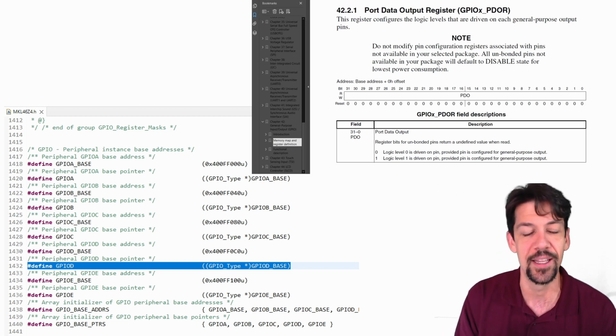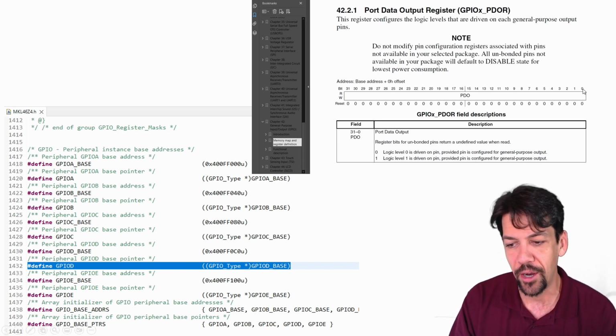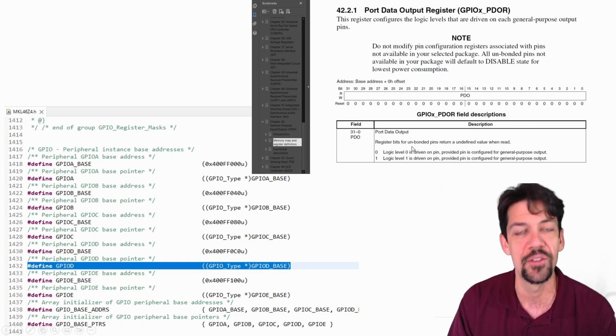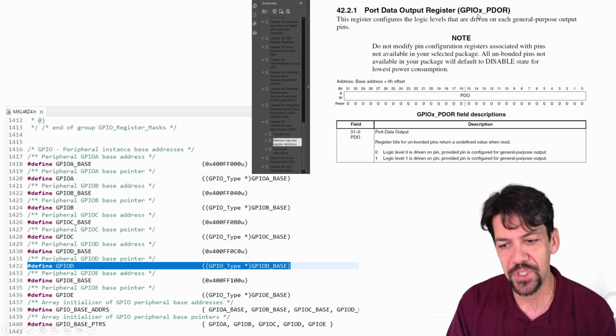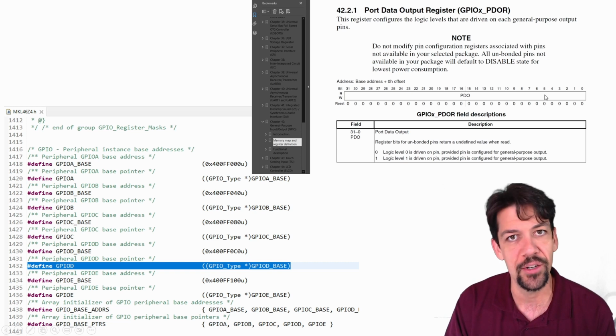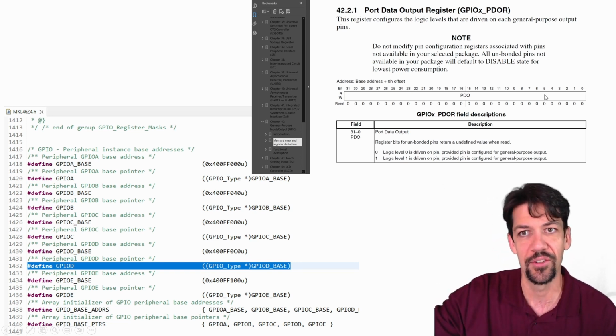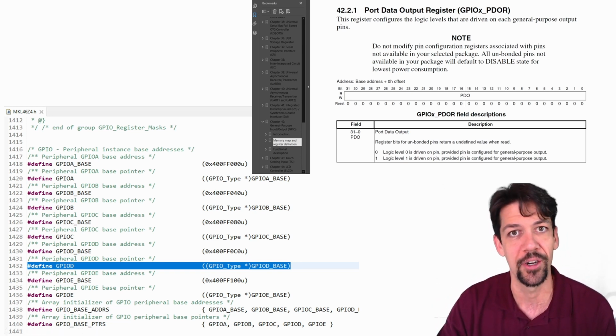space in this register. And each of the register bits corresponds to one pin on the microcontroller. So if I'm setting port D, bit 5, I'll set bit 5 in the register, and that turns on bit 5 on the microcontroller itself.